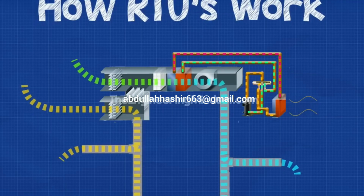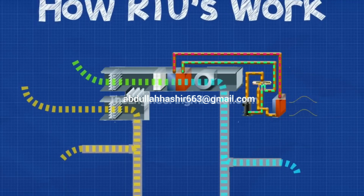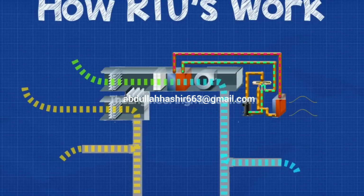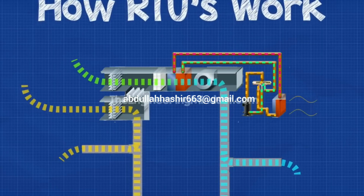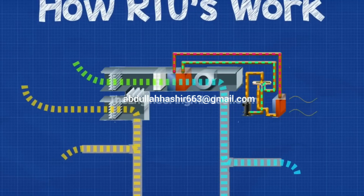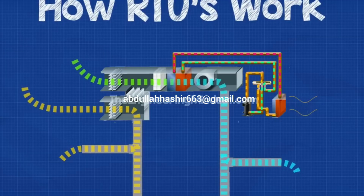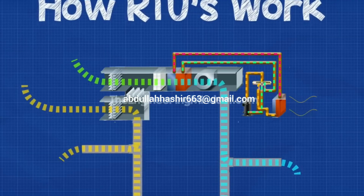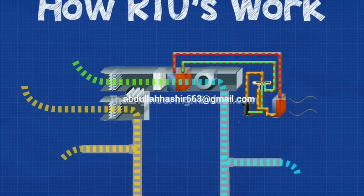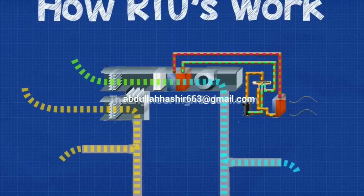The fresh ambient air is sucked in via the fan and passes across the dampers. It then passes through the filters to remove any dust and dirt before its temperature is adjusted in the heat exchanger. The fan then pushes this out into the building to condition the space. Another duct will collect the warm used air from the rooms and will distribute this back to the rooftop unit, where it will be ejected or recirculated if that option is available and the conditions are right.